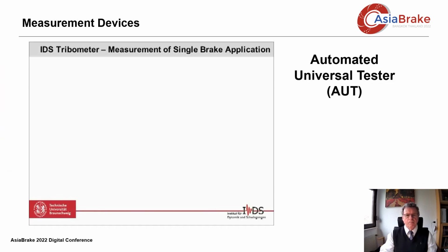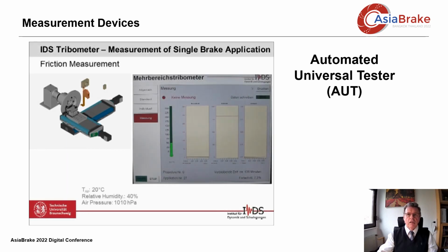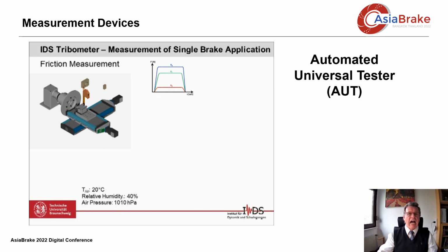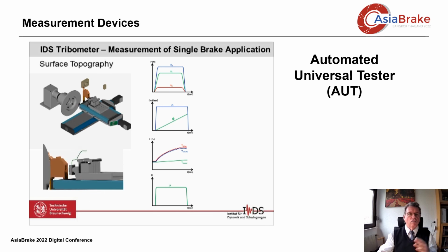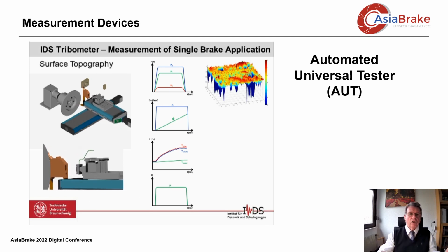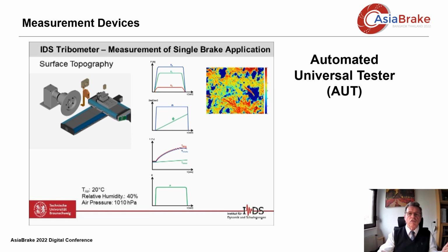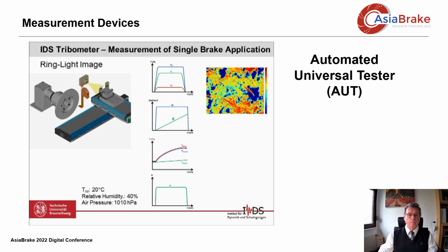Here you can see a rough sketch of our fully automated tribological tester. The pin, a 2 to 4 square centimeter pad cutout, is guided over a high-precision XY table to the brake disc and to many other instruments, for instance cameras and surface scanners. Not shown here, the Y table runs on the outer side on an additional rail to catch moments from the friction force of the disc.